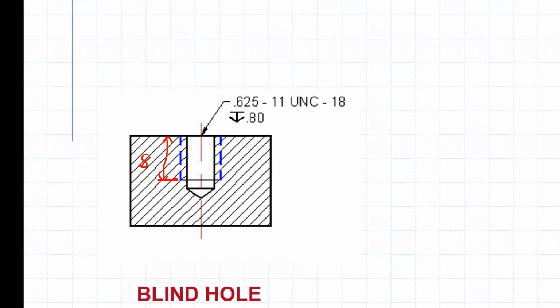And somebody else is going to ask me, well, how far do I make this hole? So does everybody understand how threaded holes are made? Has anybody ever threaded a hole? Yeah, I've done it once or twice. So the way that you make a threaded hole is that you drill first with a drill, and then you come back with another tool called a tap.